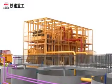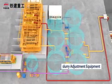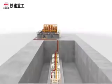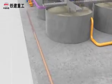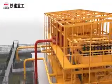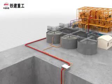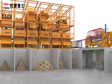The system is composed of slurry separation equipment, slurry adjustment equipment, and filter press equipment. The slurry discharged by the TBM will be pumped to STP underground through pipeline. Particles in the slurry are separated by STP. The slurry will be recycled while the mud will be stored.